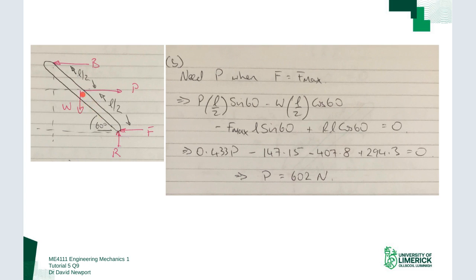The reaction force hasn't changed. So again, you just need to be careful of that. If P had any kind of a component down like that or a component up like that, then the reaction force would change. Okay, so just be careful of that. My W minus W plus R equals 0 equation doesn't change by changing P. But if this had any vertical component in it, that would cause the reactions to change. Okay, so just be conscious of that. Don't assume that automatically. We've seen that in the aircraft example already.